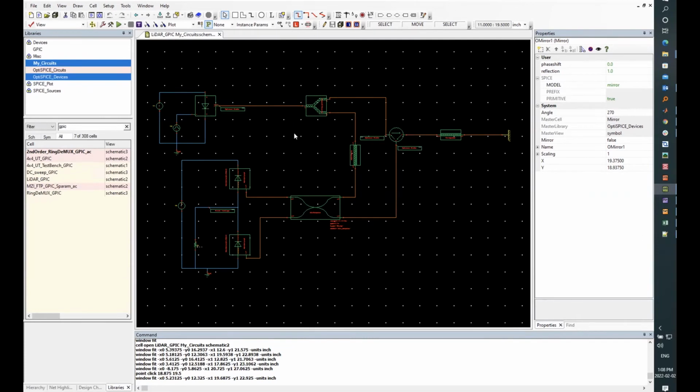And when you subtract the two, you end up with a constant difference between the frequencies. The difference between these frequencies is proportional to the time traveled between the chip and the target. So when we look at the beat frequency coming out from the photodiode, we can actually measure the distance traveled by the light. So this is the basic principle of this LiDAR simulation. You can go ahead and run the simulation, Saurabh.